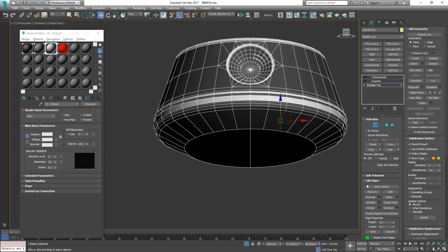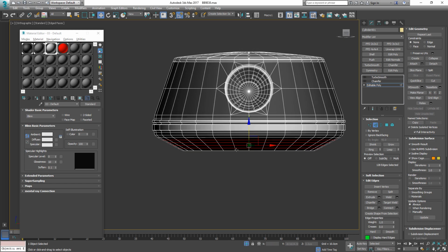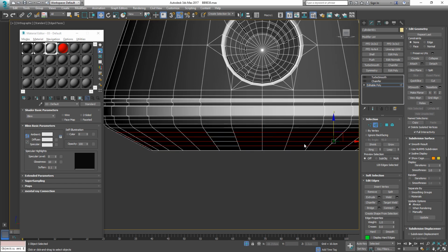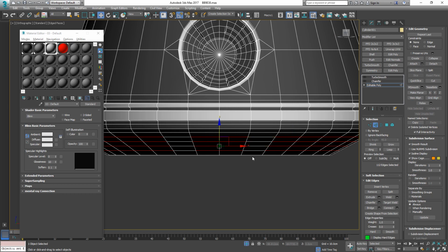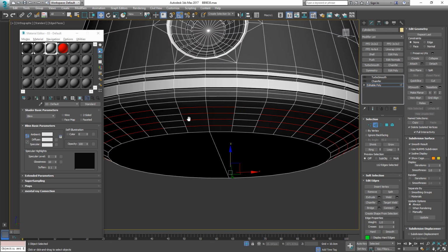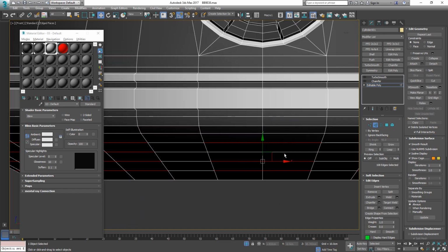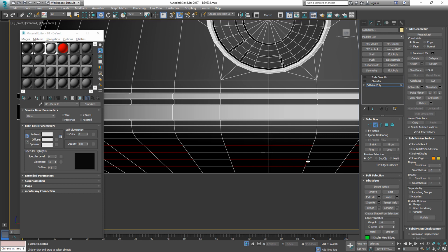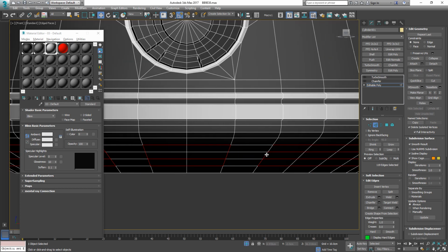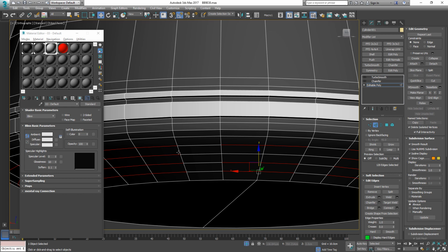And let's go back here to that segment, make a ring selection on it, and also make a connect here with 4 edges, or edge loops I should say. And now while pressing Alt, let's deselect some of these edges, which will do the same thing at the back side. Let's go to front view and deselect this edge loop here, these 2 edges, or 4 edges if you count the back side. And then let's connect these edges here at these borders. And we want to do the same thing here at the back side.